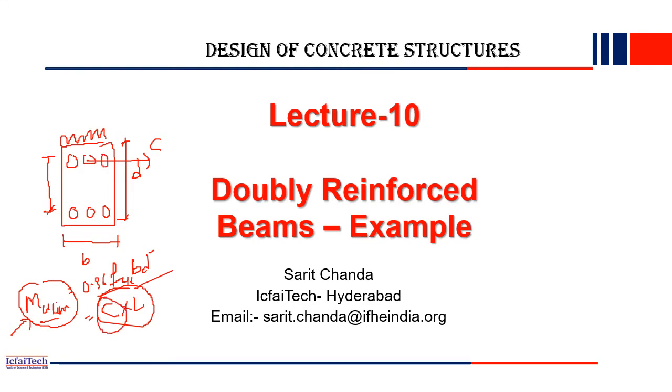As we add additional reinforcement at the compression side, we have to add additional reinforcement on the tension side also, because the section should be in equilibrium. Whatever the total compression force is, the same amount should be the total tension force. That is the balanced section we have to design. That is what we discussed in detail in the last class, the theory part of the doubly reinforced beam.